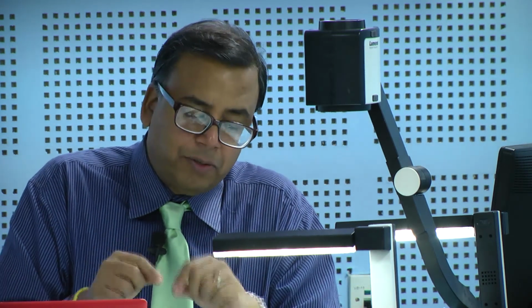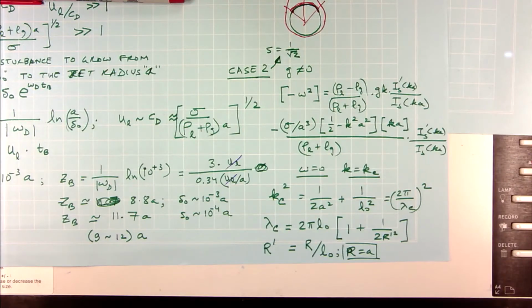Okay. So, when you are designing your boiling heat transfer experiment, now you got to figure out what diameter heater should I use. Now, the more fundamental question becomes, at what value of R does my lambda c become independent of the diameter of the heater?